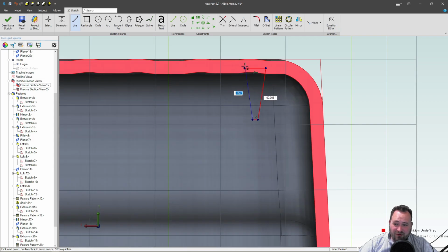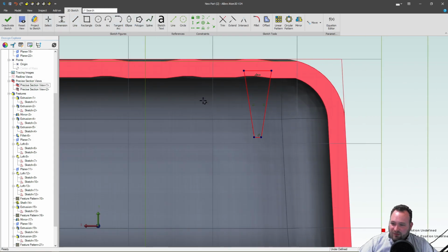Again, a lot of injection molders will break the rule and go a lot longer on the ribs. There are risks associated with that. You can get sink up here, where there's so much material down here that as the plastic cools, it shrinks and it sinks this top surface that the rib is under. That is a distinct possibility. You also can get short shot, where if you try to run plastic so long and so thin, it may not fill the cavity all the way, and it dries out before it's full, and then you just don't have a complete injection mold like you've intended. So that could be a problem.